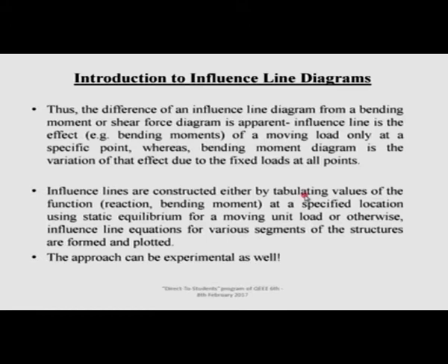Most of the time we will be tabulating the values at critical locations and joining them with lines, which are suitable for statically determinate structures. We will see that they are straight lines, and we will explain why. For statically indeterminate structures, they are curved. So, an equation may be better, but sometimes it will be cumbersome. So, we will go for determining the values at discrete locations.